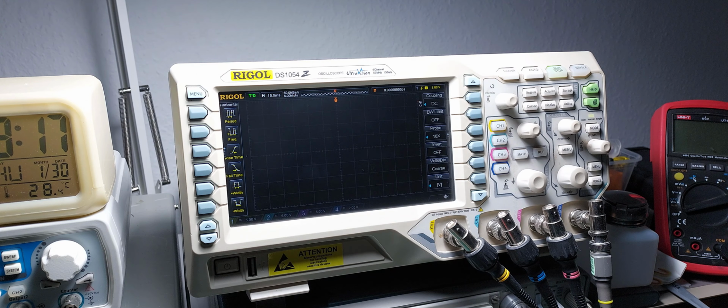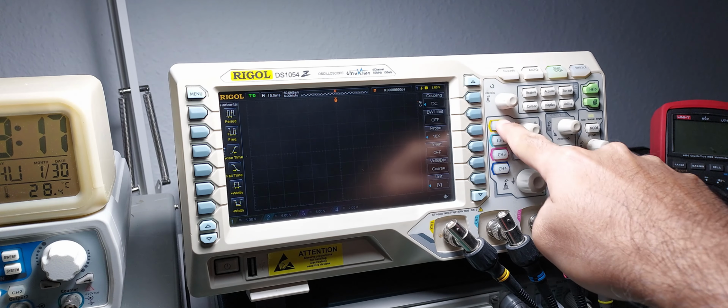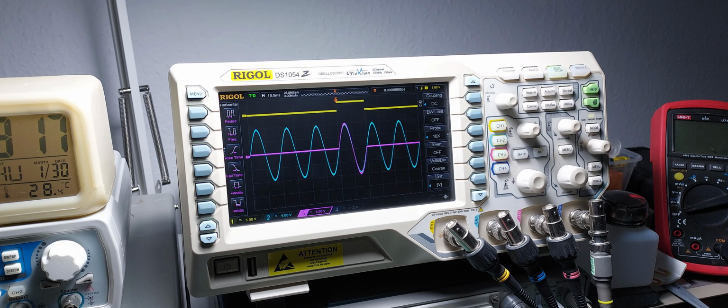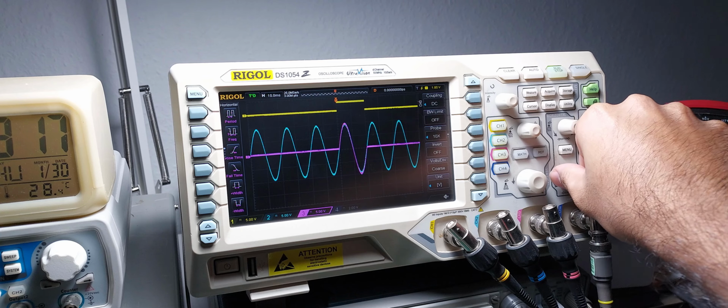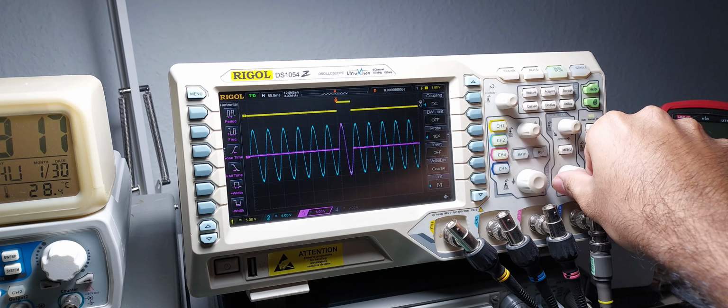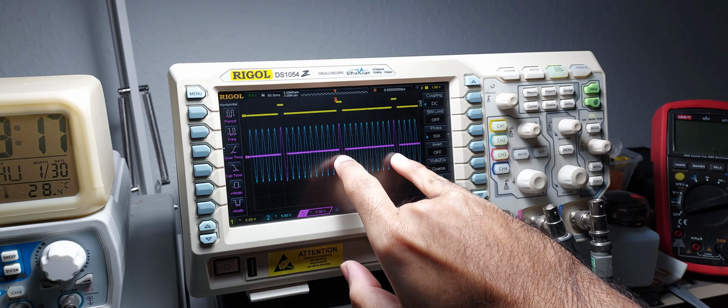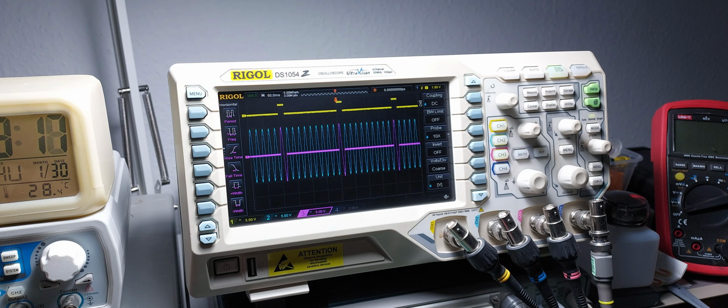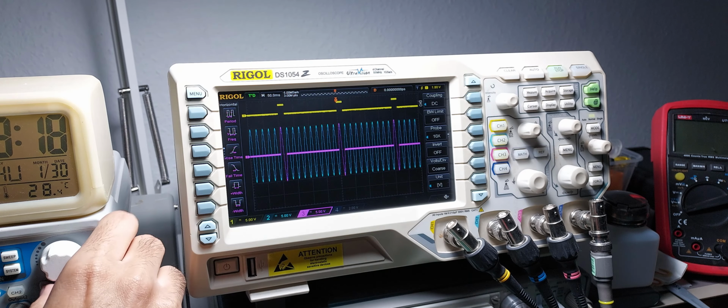Even the most basic discrete implementation of this circuit performs surprisingly well. Here's the sample signal, the input waveform, and the output of the circuit, which follows the input when the sample signal is high and holds the sample voltage perfectly, a testament to the incredibly low bias current of the OPA140, the dual version of which I used to build this circuit.